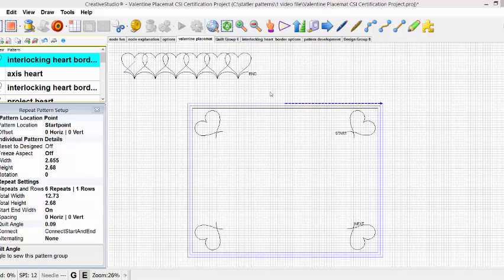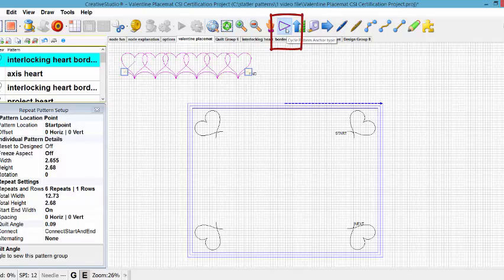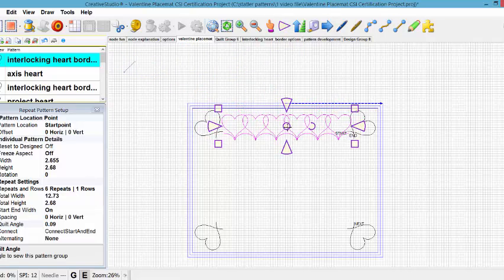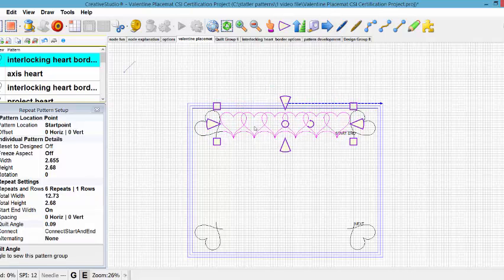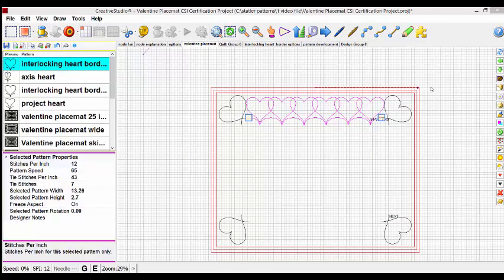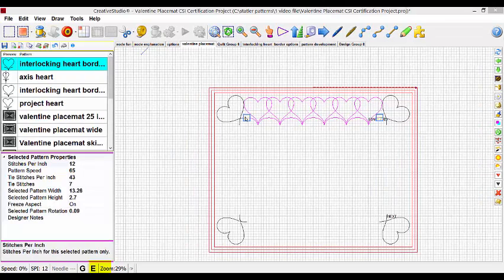Select and move the border pieces over to your project and center them between the top two borders. This can best be done using the edge anchors. Select the Cycle Pattern Anchor type on your toolbar and click it. You will come to the purple edge anchors. Put your border in between the two corner pieces. Change to your blue endpoint anchors. Activate the end snap on the status bar and snap the border to the corner pieces.